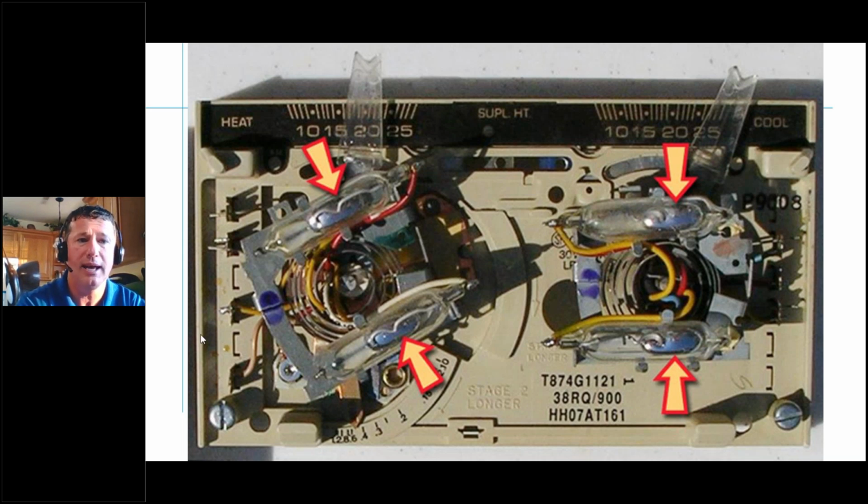So let's look at the ones over here on the right. If we look at these two, we can see that the one that is closest to temperature is going to be relatively horizontal, and the one that's going to be pitched off a couple of degrees has got just a little bit of incline to it. So it's at a slightly different angle than the other mercury bulb, just so that we can get a little differential between them. So we can stage our thermostat based on the angle of levelness in our mercury.